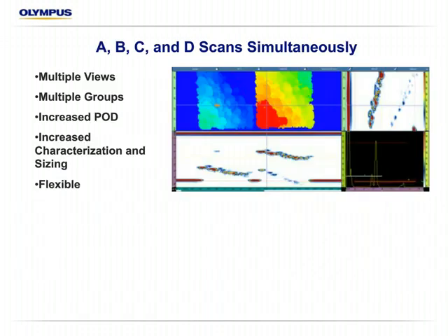So a lot of the views we look at are the same, but with phased array views we have a lot of flexibility, and we tend to look at more volumetric views. We still use the C-scan, or the top-down thickness scan, as our baseline, but from there we can start to view side views simultaneously along with the raw A-scan in order to do a really good assessment of what we're looking at. This becomes inherently important when you do have something beyond general wall loss, something like HIC or SOHIC, or just a mid-wall anomaly that you weren't expecting in your corrosion scan.